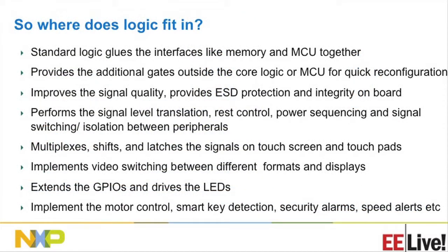So looking at the standard logic, today it's gluing the different interfaces like memories and MCUs together. There are some additional gates outside the microcontrollers for quick reconfiguration. It's still improving the signal integrity and signal quality. It also does some ESD protection. On the boards, it multiplexes, shifts, or latches the signals, and sometimes we extend the GPIOs and drive the LEDs with them.